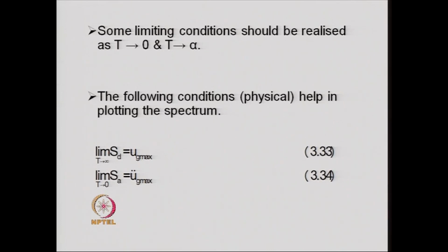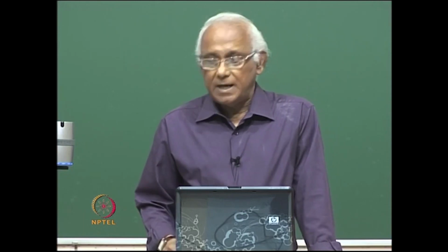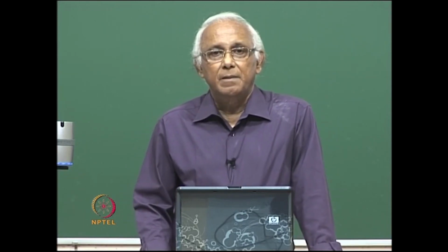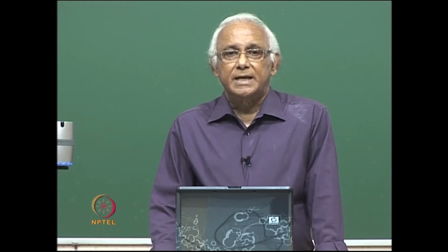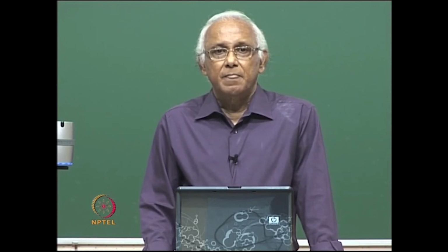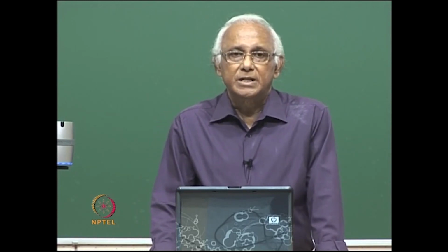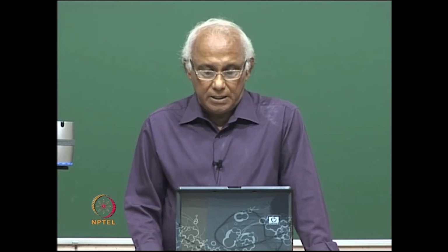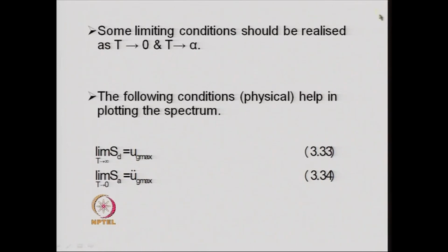It is a graph in which we have four ordinates. One is the horizontal axis in the log scale, the other is the vertical axis in the log scale, and two other scales, which will be inclined lines perpendicular to each other and also defined in a log scale. These four axes define the quantities SV, SD and SA for a given omega n value.